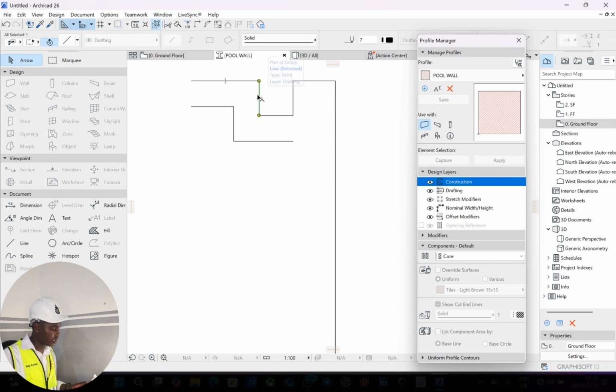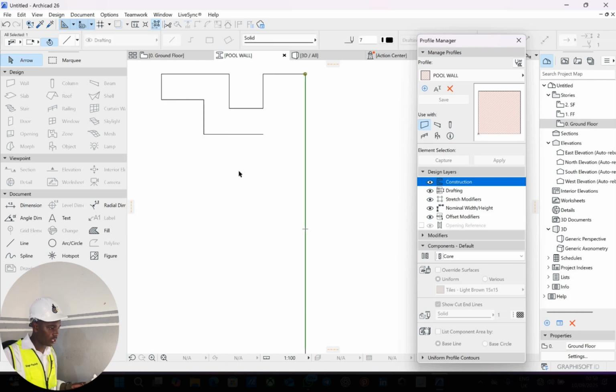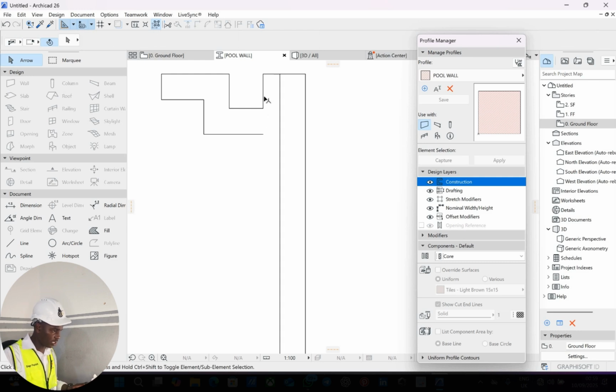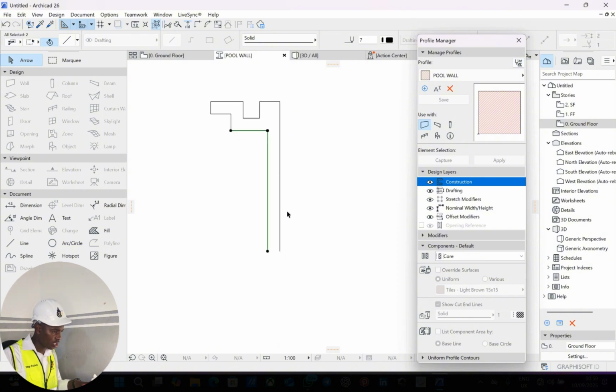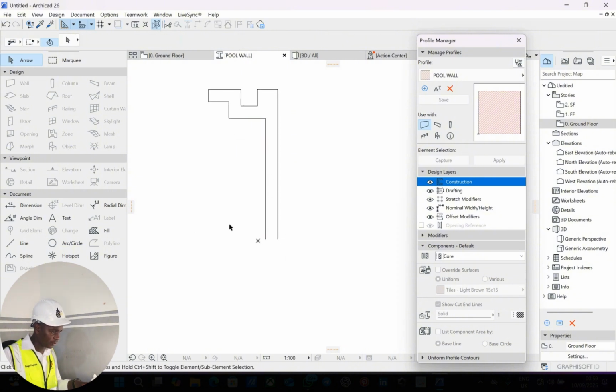The distance I think is 40. Ctrl Shift D, 40, duplicate it at 40, click enter. You can delete this line, it's of no use. Then here also Ctrl Shift D, 15, enter. Then you intersect. You take again 15 here. Okay, you intersect directly. To intersect, I told you already how you are going to intersect. So this is what you have here.